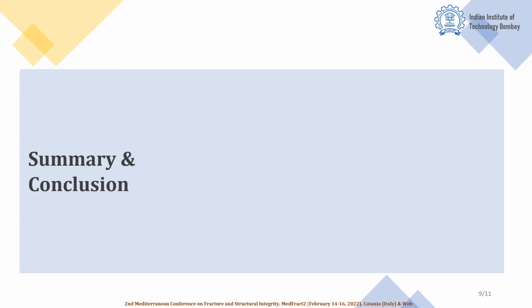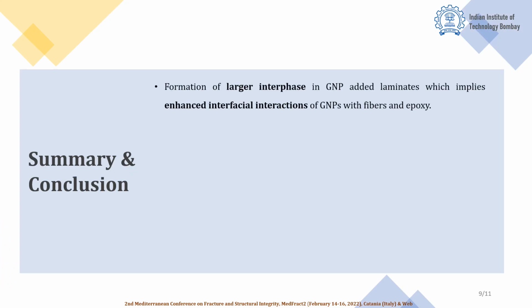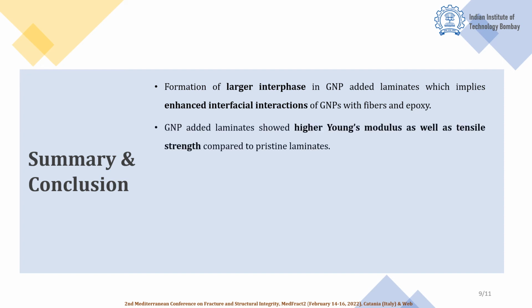This brings to the end of my presentation. First, we looked at the formation of a larger interface in GNP added laminates, which implies enhanced interfacial interaction of GNPs with fibers and epoxy. And we saw that GNP added laminates showed higher Young's modulus as well as tensile strength compared to the pristine laminates.